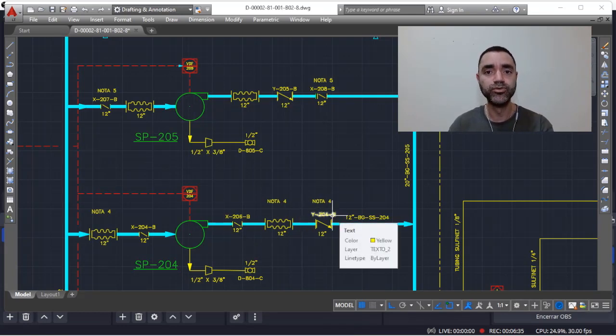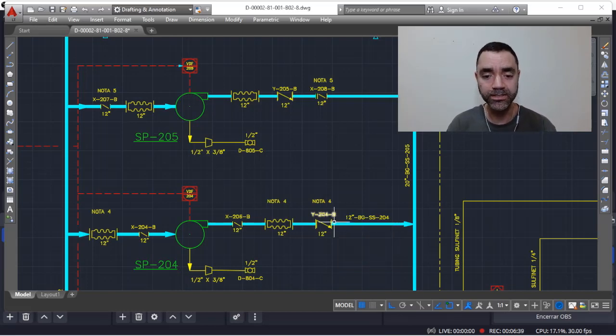In this case, to repair the system, we need to remove the internals of the check valve, do the maintenance, and return to operations. As the check valve is installed in this arrangement, we are not able to keep up the production because I am not able to isolate the check valve from the downstream process.